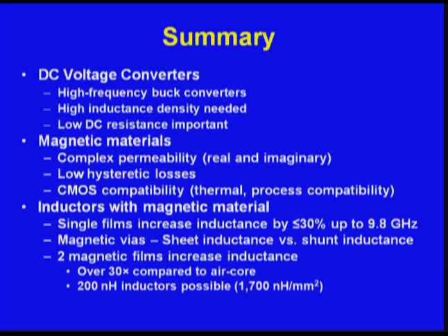Thermal is another issue. Not only thermal during depositions, but thermal when you're using it. Does that affect the magnetic properties or not? We've had cases where the deposition process for putting down the dielectric supposedly never reached temperatures above a couple hundred degrees, and it turned out that it was not cooled in one particular part of the process, which caused the temperatures to go high enough that it actually caused the magnetic material to fail. And nobody could figure out why, because the people who knew that tool were certain that it never went over those temperatures, but sure enough it did.